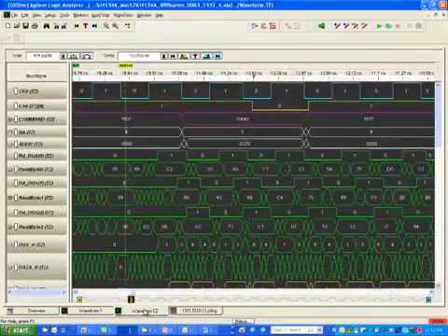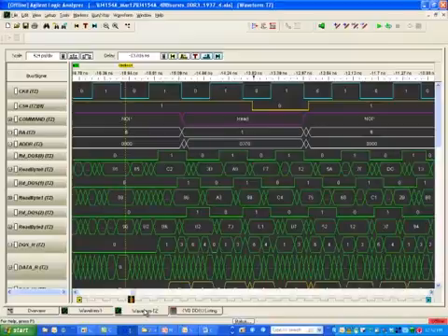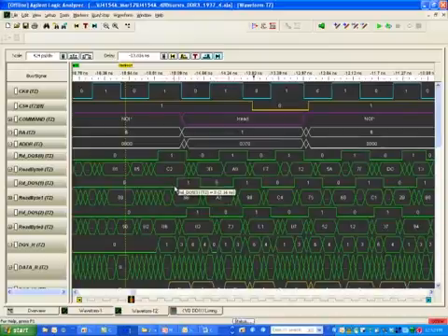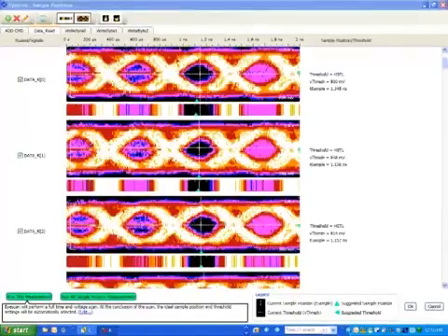Moving to the timing zoom window, here we have a high-resolution capture of all signals on the bus. Of particular interest would be each strobe with its associated data byte, where we can observe the flyby routing. To understand how the U4154A provides the highest confidence in measurement accuracy, we open up the Thresholds and Sample Positions window from the Sampling tab.